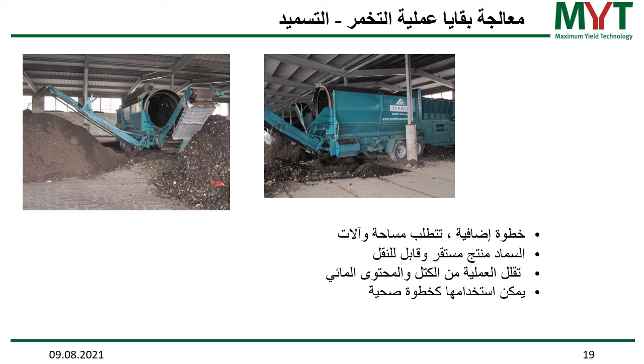Digestate handling, one aspect is the composting process of the solid fraction. This is an additional step which requires area, because usually you use windrow composting and there's a certain area demand for windrow composting, and you require machinery to actually conduct such a post-composting process.